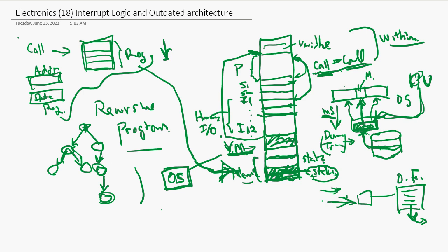Okay, when the software manages it, every call or interrupt initially has a section of the program. Push means each register is pushed onto the stack. Every register is stored by each push going up, and the address and the data pointer are saved, and a bunch of pushes are executed. Okay, and that's a way to create a stack.